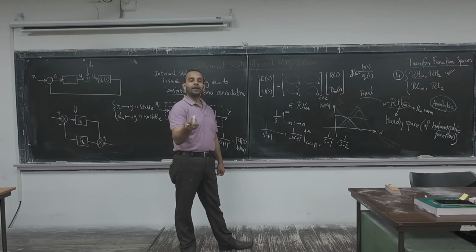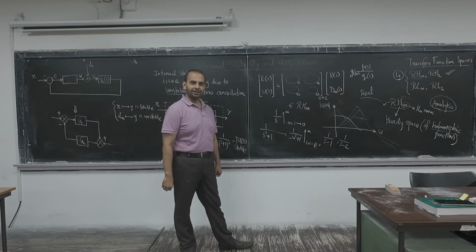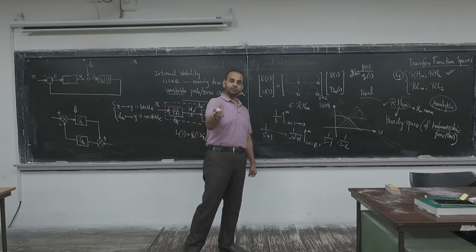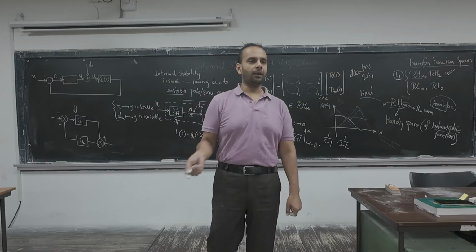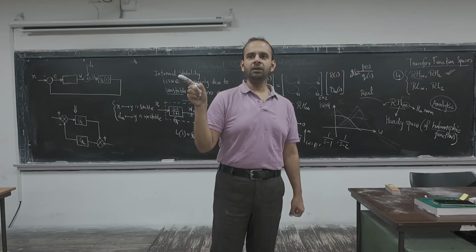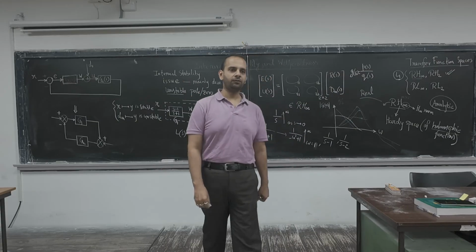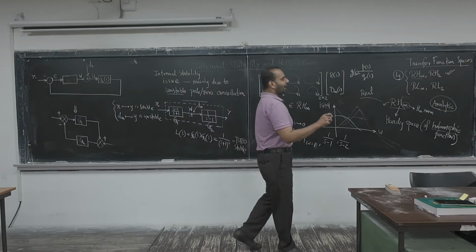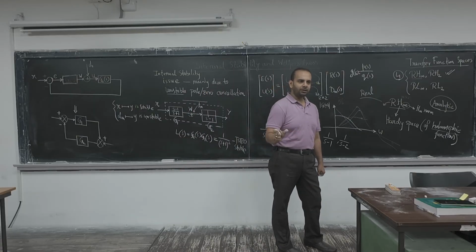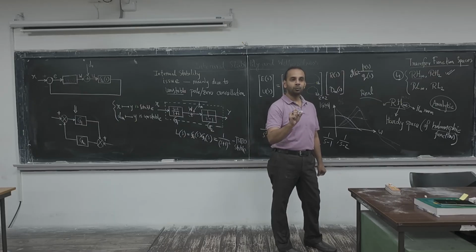Then what is the crux? Any transfer function with a pole on the j omega axis or in the open right half plane is an example of an unbounded H infinity. So in that case, the H infinity norm is not defined. I mean, when it is going to infinity, the norm is not defined. Because when we say this object has an H infinity norm, or any kind of norm, that means the norm must exist. What is the meaning of norm? It must be a real number.